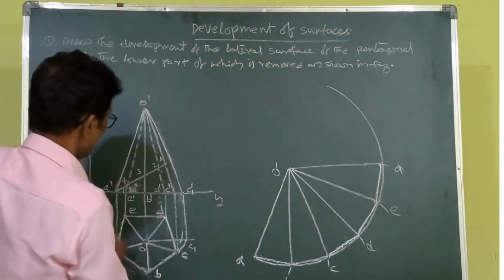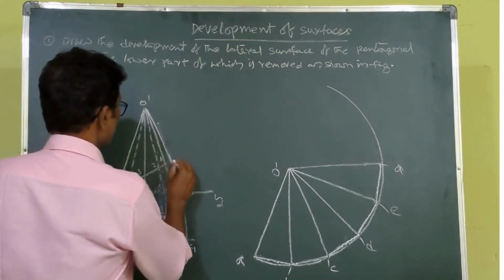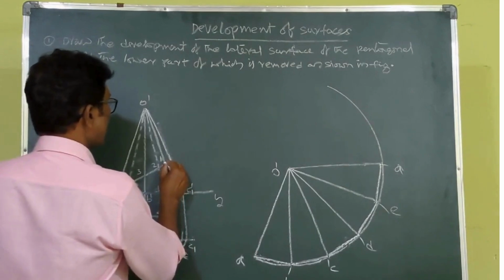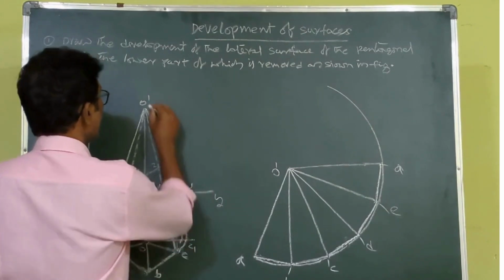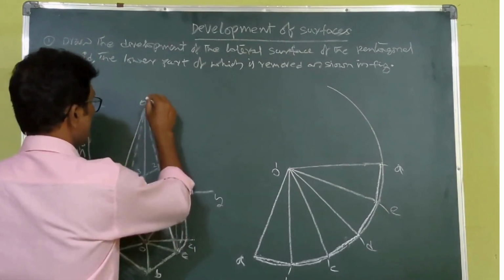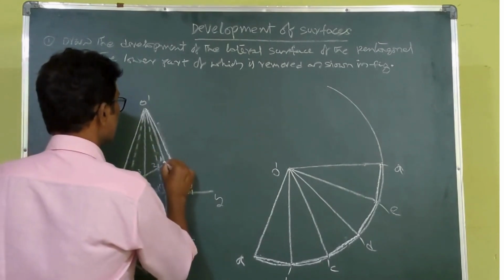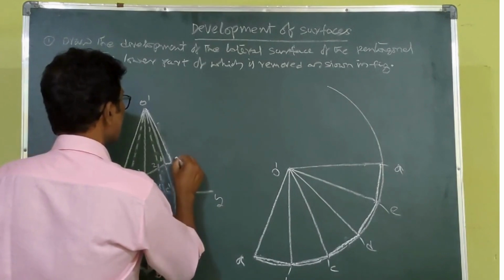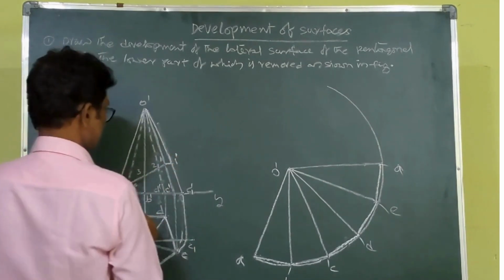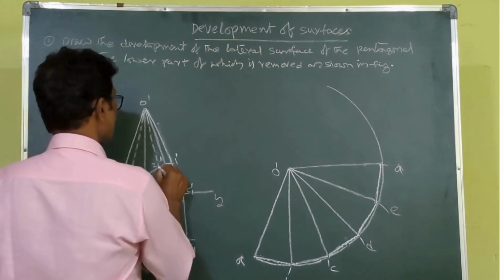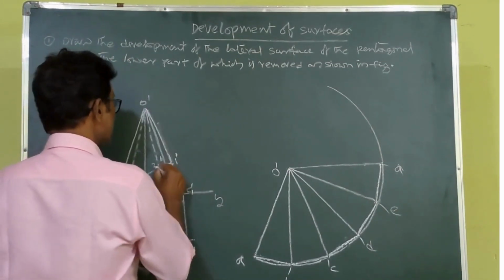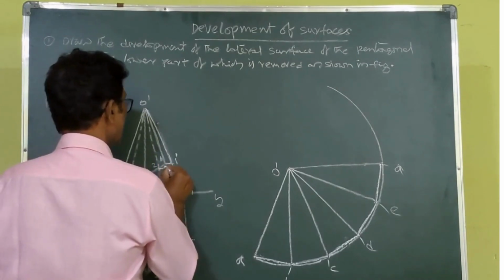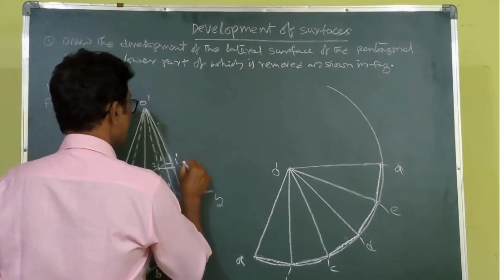Now then you see here. This is the true length. I want to get the true length from that 1. You draw the horizontal line parallel to XY, O dash and C1 dash. Horizontal line. Let us say that is the O dash. At 2 also you draw a horizontal line with respect to XY onto this O dash and C1. This is the 2 dash.